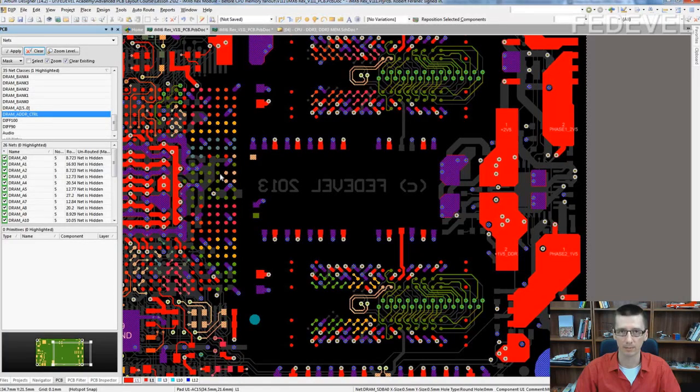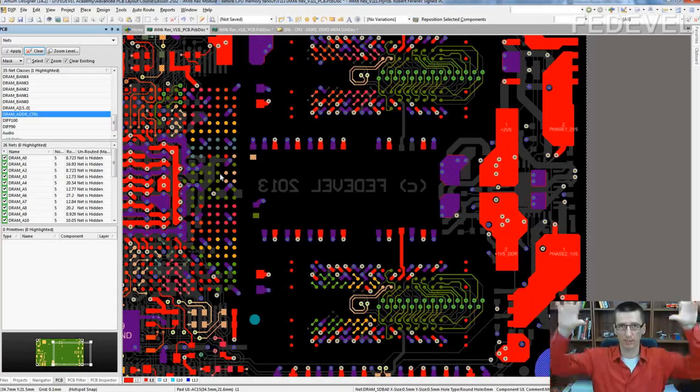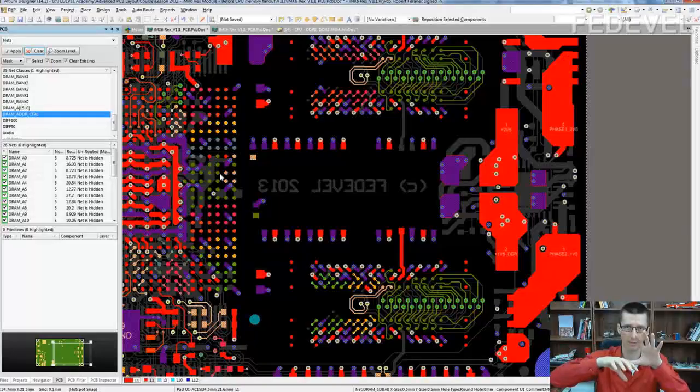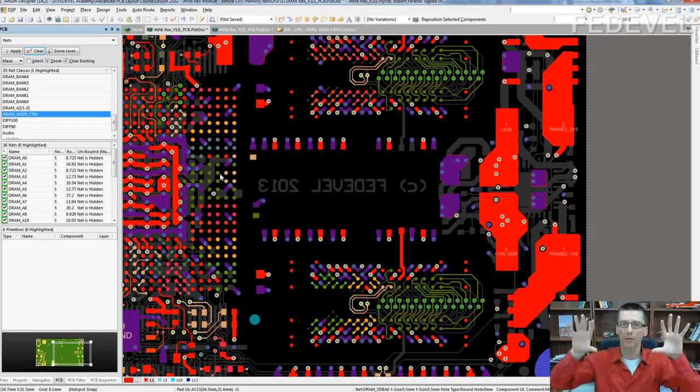From the middle. If you start doing layout from the processor edges, you start drawing the tracks and you go into the middle. Later you may find out there is not enough space to connect all the tracks in the middle, and you have to redraw everything you have done.